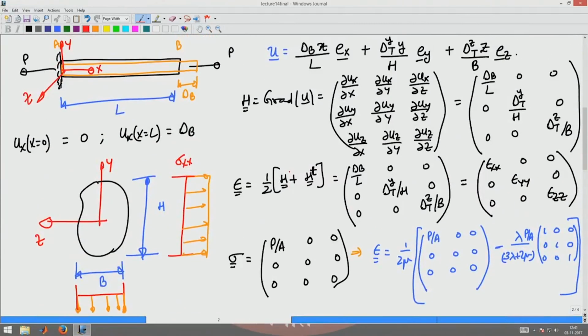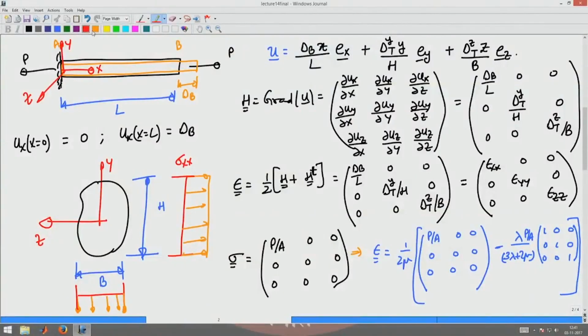Okay. One is you can use this expression, find the elongation in the axial direction and the contraction in the lateral direction to find the strains. You can use these expressions to find the strains from overall displacement, or you can use a strain gauge and measure the axial and transverse strain. Okay. We saw what a strain gauge is in the previous lecture.